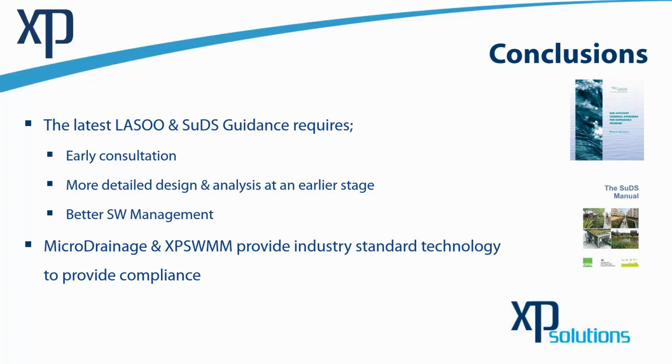But at the north side of the site where we did not have any information, because it's time consuming and it involves money to go and get information from either local authorities or water companies who own the networks, we can just assume a worst case scenario where it's completely flooded, which quite often happens in this country when you have 1 week of rain and everything is just surcharged. That's right. That's a good point.